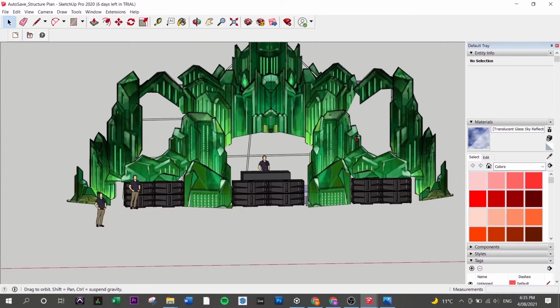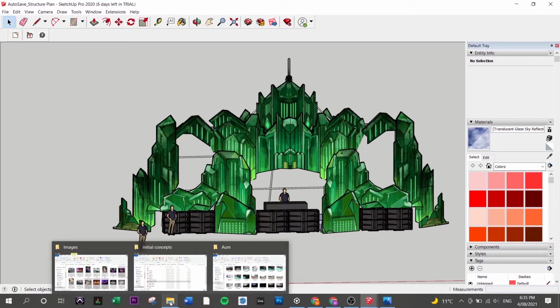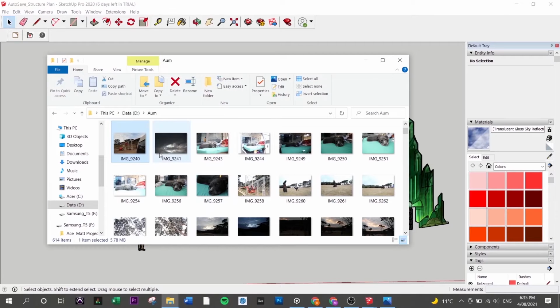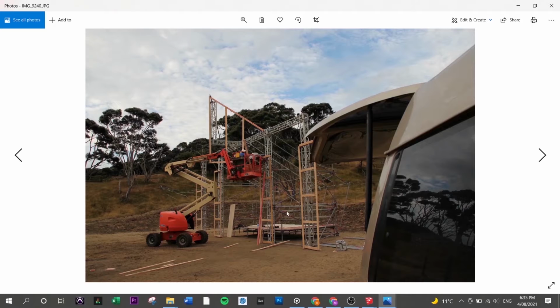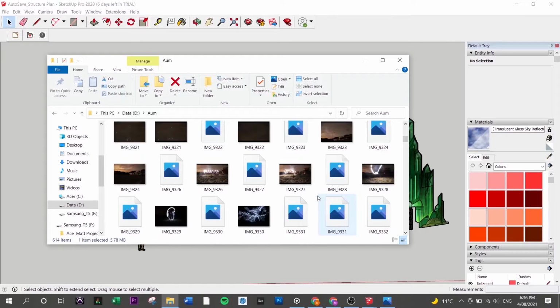So this is what we ended up coming up with. What that looked like at the end. This is us starting it off. So the scaff and the truss was all made according to the plans. We started framing it out. The way that I'd done it is I'd placed these frames out in 1200 millimeter centers. That was the size of the core flute sheets that were available, and then we just built on top of that. I'll show you guys a few more progress shots.